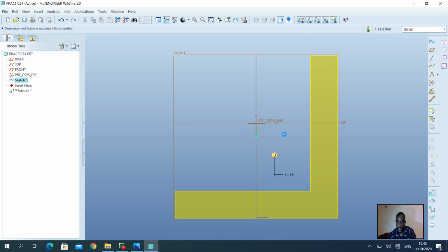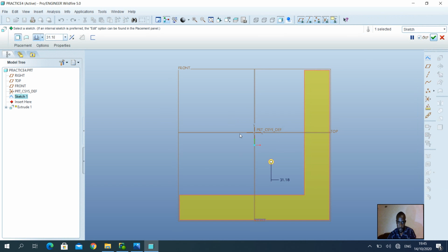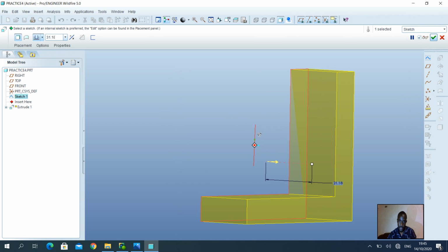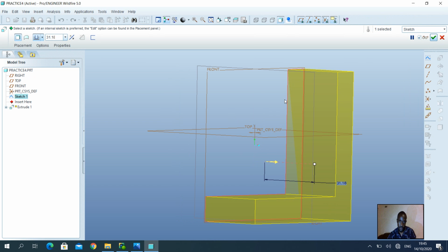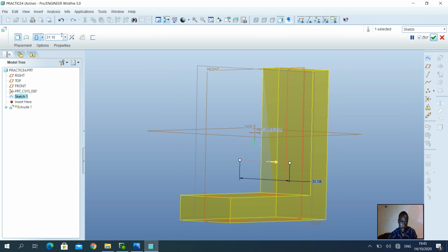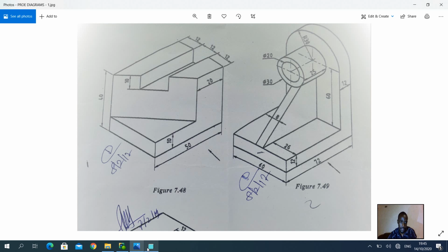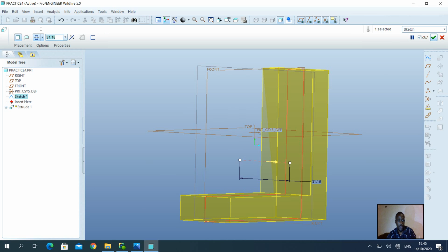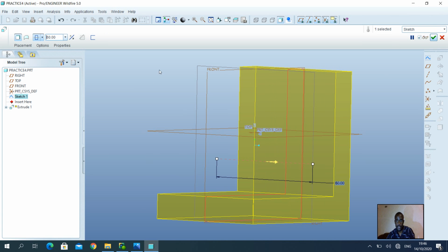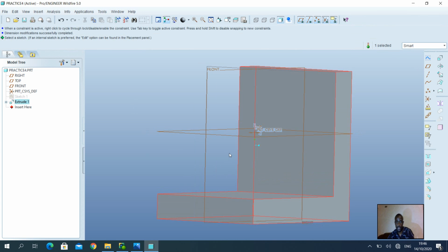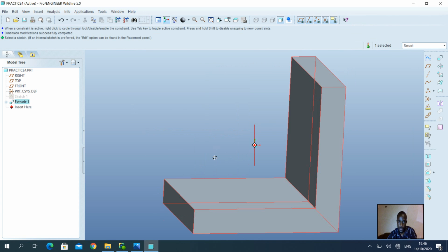By selecting the extrusion option and seeing how this thing is extruding. I want to extrude on both surfaces, not on one side of that, but on both surfaces. An extrusion distance of what? 60. So I have to indicate 60 right there. I'm going to be happy with that. I don't need to visualize or to zoom into that.